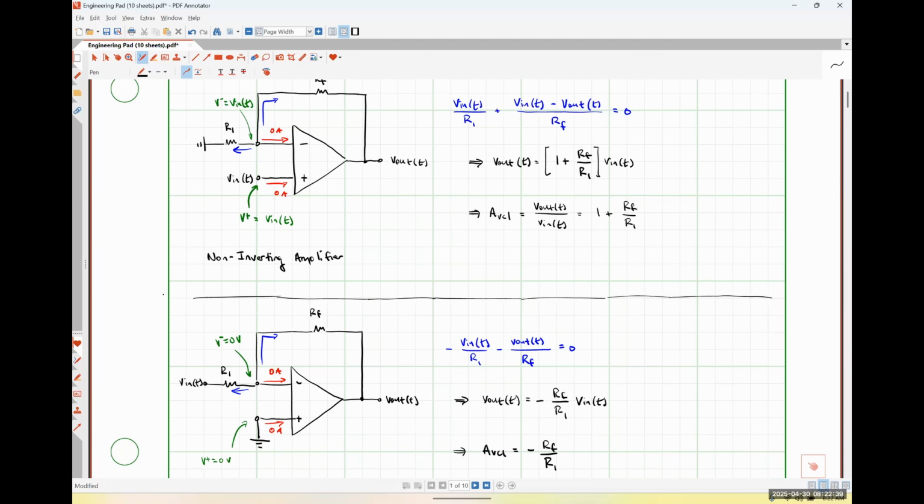So typically speaking, you might take the output signal of this particular amplifier and run it through a second inverting amplifier with a gain of 1 to correct that back to a positive signal if you wanted to. For a whole lot of applications, that negative sign is not going to matter at all. It doesn't matter that the input signal and the output signal are 180 degrees out of phase.